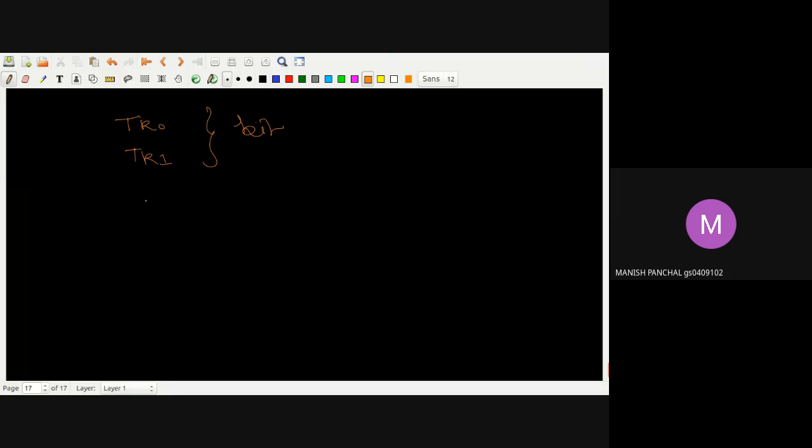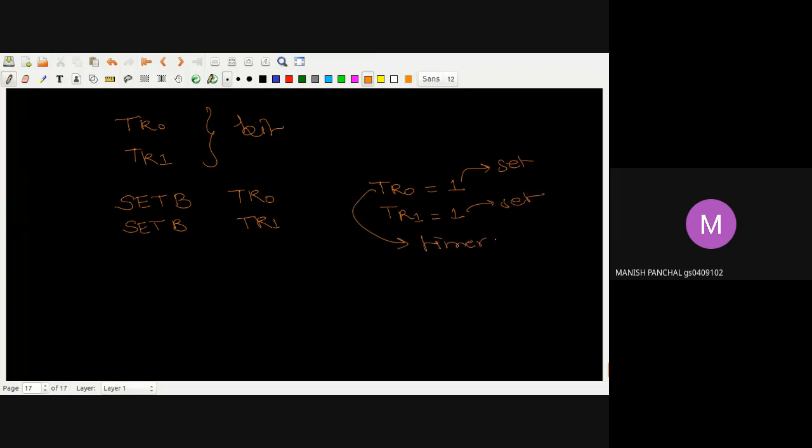तो TR0 एक बिट है, TR1 भी है। माइक्रो कंट्रोलर के पास बिट को सेट करने के लिए जो इंस्ट्रक्शन है वो है SETB, जिसका मतलब होता है सेट द बिट। अगर मुझे TR0 को सेट करना है तो मैं इंस्ट्रक्शन दूंगा SETB TR0। इसी तरह TR1 के लिए SETB TR1। इससे क्या होगा, this TR0 will change its status. If previously it was 0, then immediately here it will become the 1. Okay, and similarly the next one TR1 will become 1. Okay, so this one is corresponding to set. If it is set, then I will say my timer 0 will start.